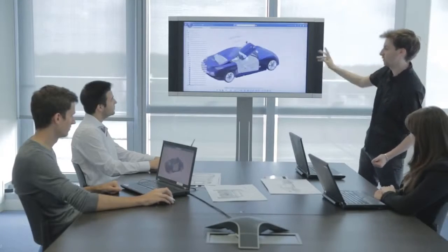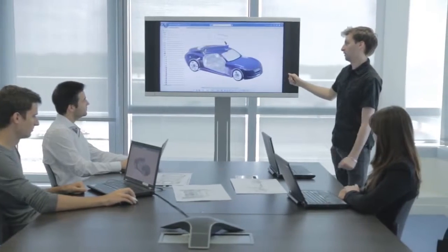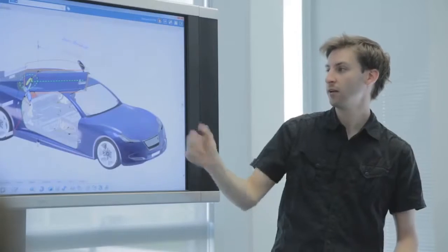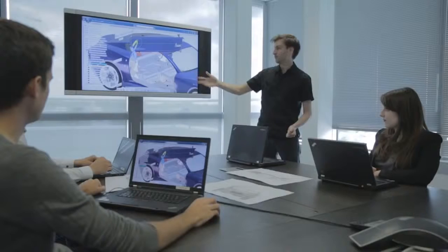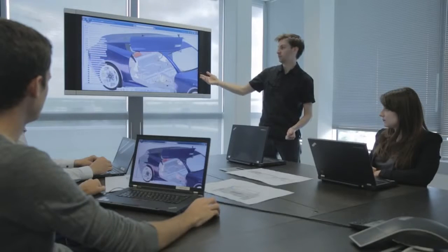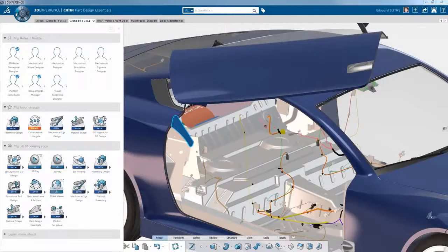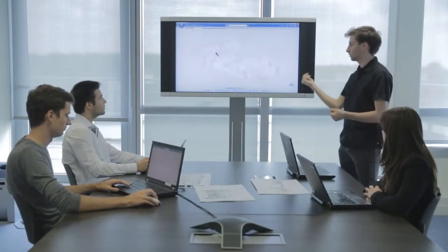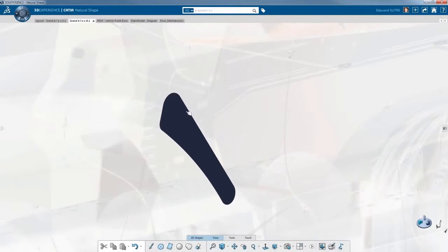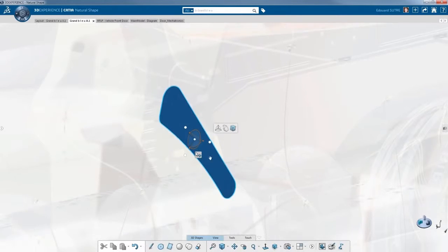We can directly switch to my 3D view and start building the complete mechanism and part design through this 2D sketch early study. So this is exactly what they will start to do. This is where you are using, for example, CATIA Natural Shape application, where from this sketch they are directly manipulating a shape from the profile, pulling the thickness of this part, and they will drive all the design of the mechanism based on this CATIA natural shape.